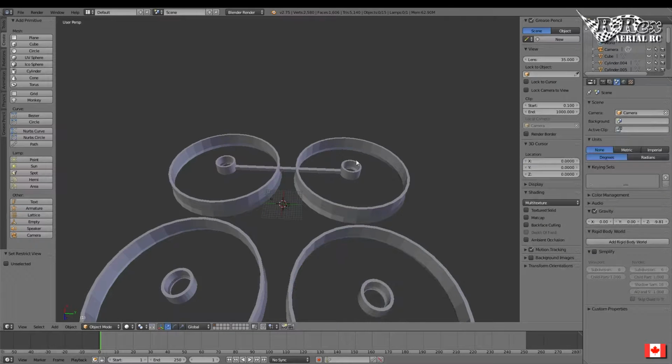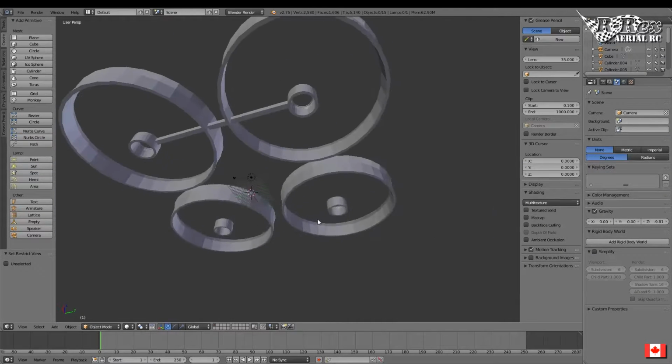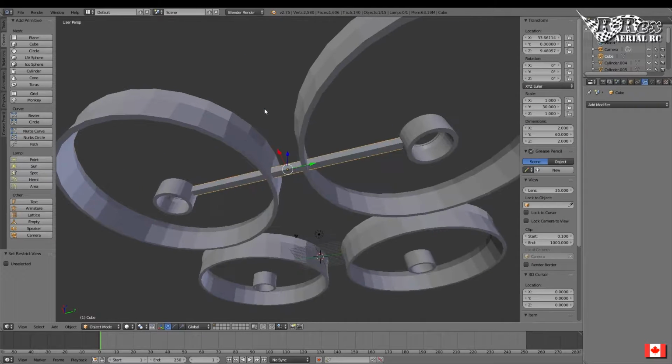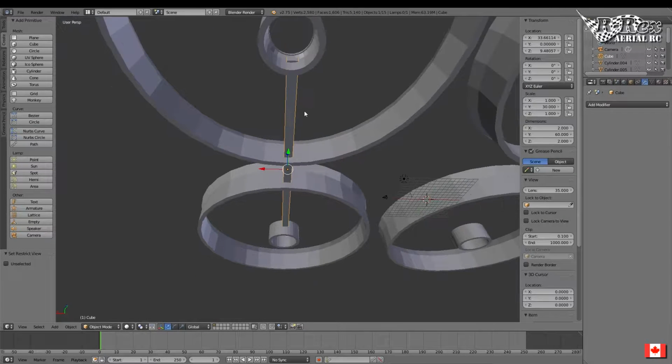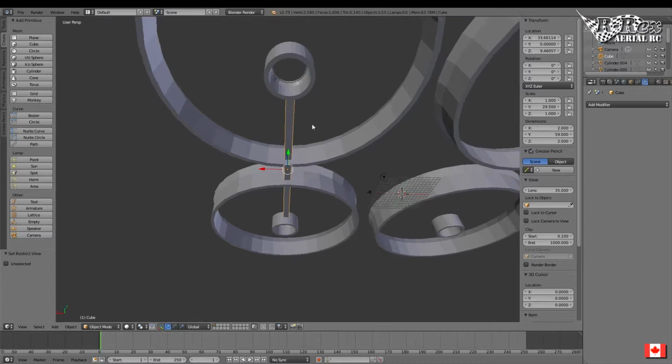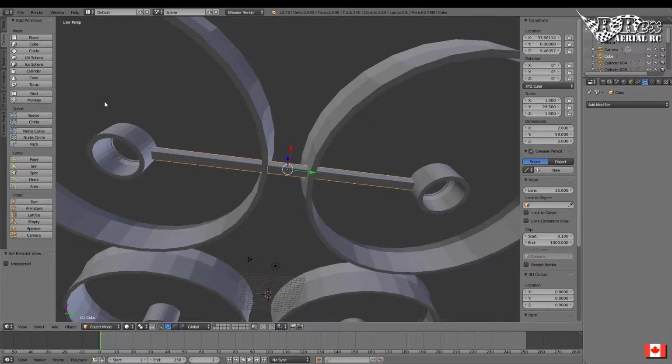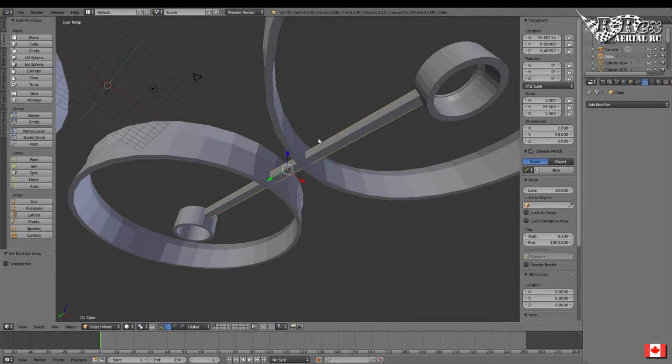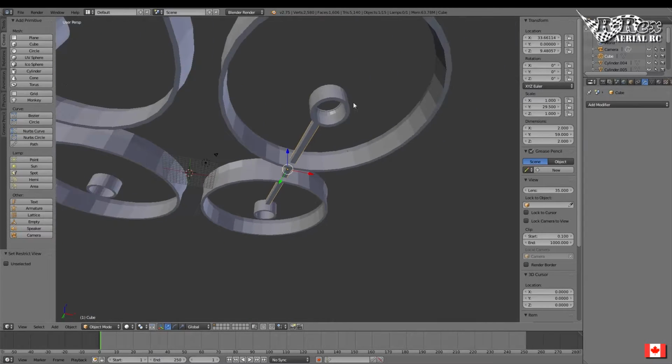And hide it. Okay, so now we have this. So we want to make sure, first of all, that we're not protruding into the other object, and we are. So 60 was just too far. So let's go 59.5, still too far. 59, there we go. You'll see that the object is no longer protruding into the other object. And the same goes for there.